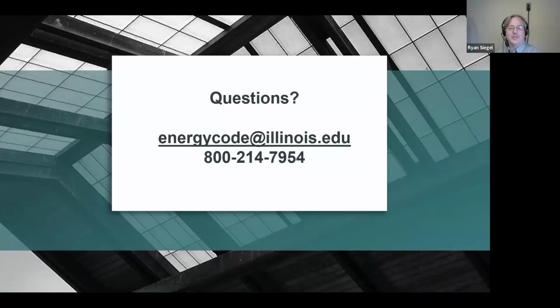Okay. Car washes. How do car washes deal with the 2021 code? That may depend on if it is designed for human occupancy. Oftentimes I've seen car washes, they'll have a little office area or something like that. That area needs to be done in compliance, but the actual wash bay itself that the cars are driving through, typically those would not be included as part of your energy code compliance checks. Part of that is they're going to probably be more insulated for freeze protection than actual people. I was thinking they'd probably go back to the definition of conditioned space. Do those tunnels contain conditioned space? If they do, you may have some compliance requirements there. If they don't, you probably don't. But as Ryan said, you're probably going to be insulating more for freeze protection than anything else in that case.